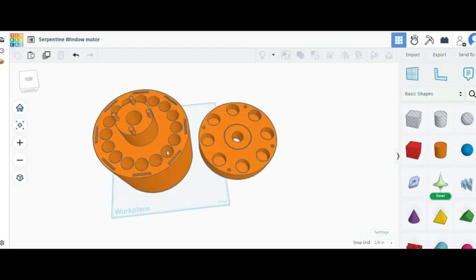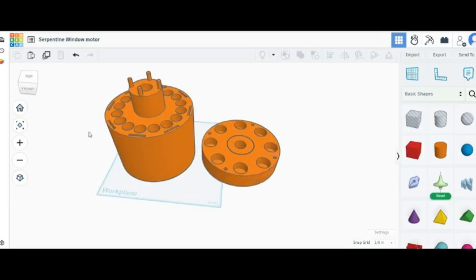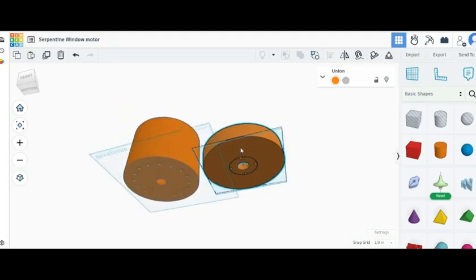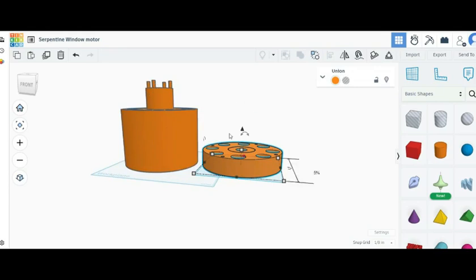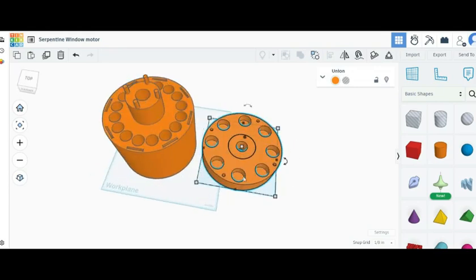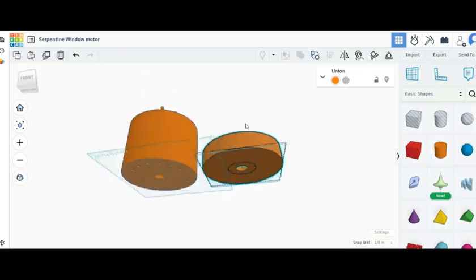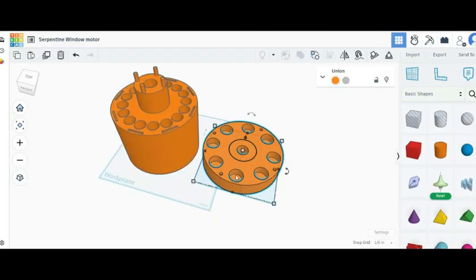You have some slots to put in some mass there, and because the coil is going to be taking up the whole outside, you put this part on here, and then you have this part here, and you see those will slide over that, and then this part will go in there, and you'll put your magnets here. And you can see that this is lined up with this, and so when that fits in there, each of these magnets will line up with one of these.